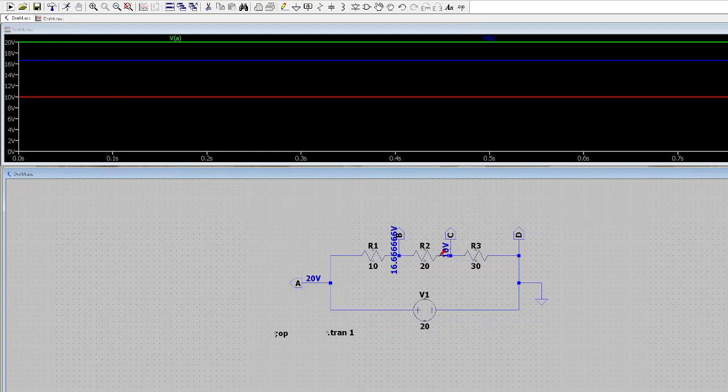However, we can see that the voltage measured across 10 is 16.6. This is in reference to ground. I have said that before. And the voltage at 20 is in reference to ground, so it's not measuring only the voltage across 20, but the voltage drop across 20 and 10, across the two resistors.